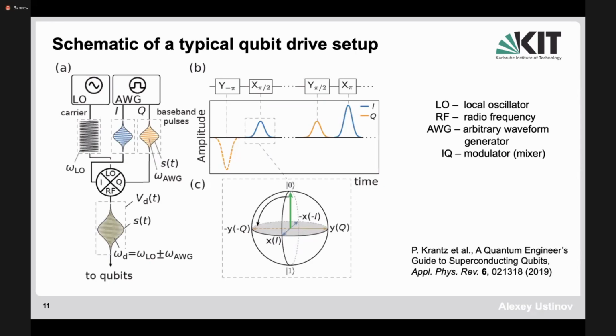When you have a cell phone in your pocket, then you have basically a device which converts the frequency received from the external antenna into the quadratures of the reference signal, which means that you always up-convert and down-convert the signals from a particular frequency down to the low frequency range of the intermediate frequency.